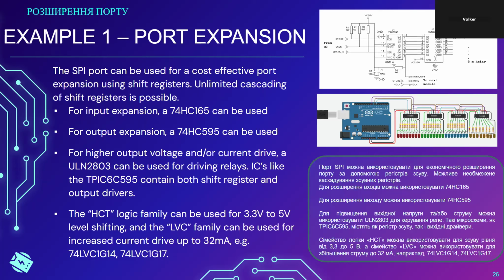You can set up UART, you can set up SPI, you can set up the I2C interfaces. It's probably easiest to do with SPI and also UARTs, so that data will be coming in and collected in specific memory areas on the microcontroller and can then be processed in blocks.